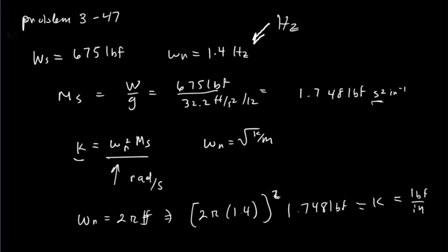In this case, the deflection then is going to be about 4.99 inches. So for that ride rate and for that load, we'll get a deflection of about 4.99 inches. So this is just one way to do that.